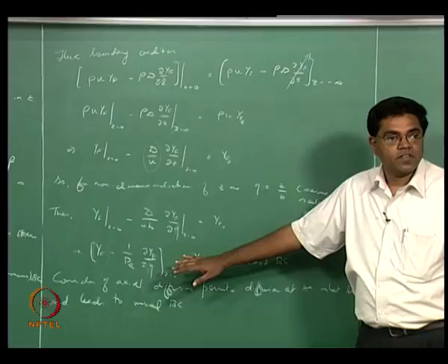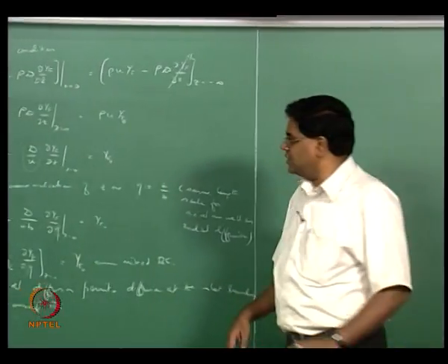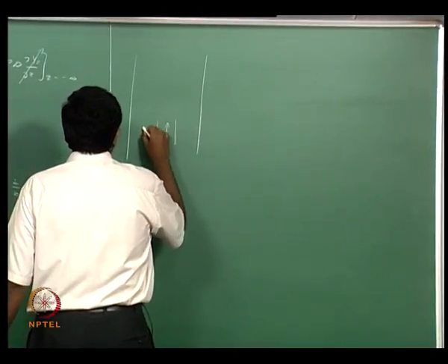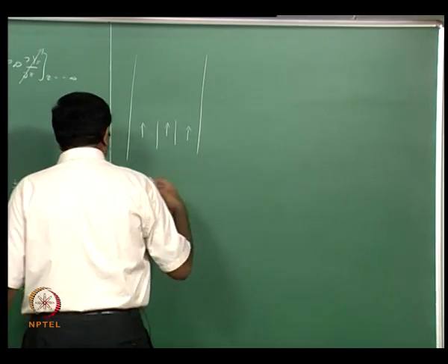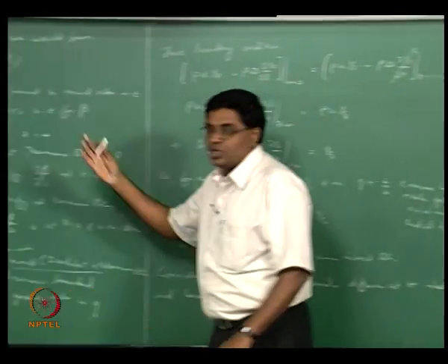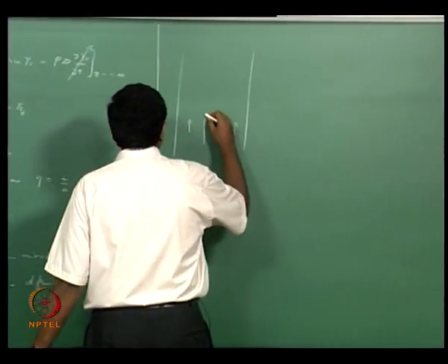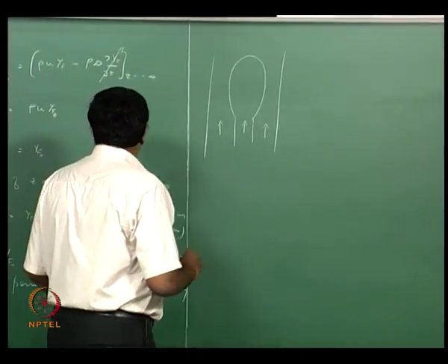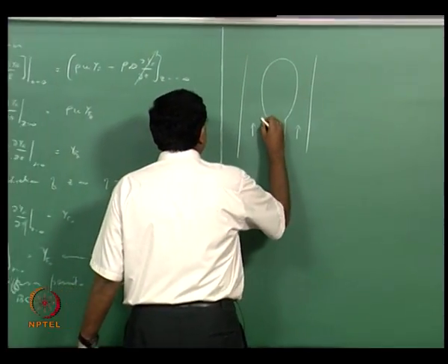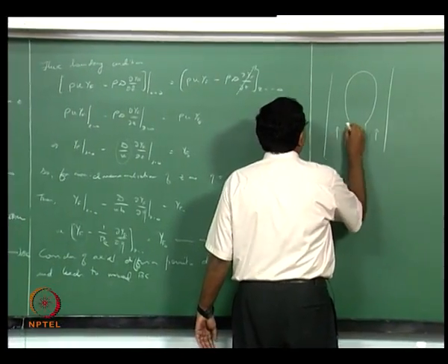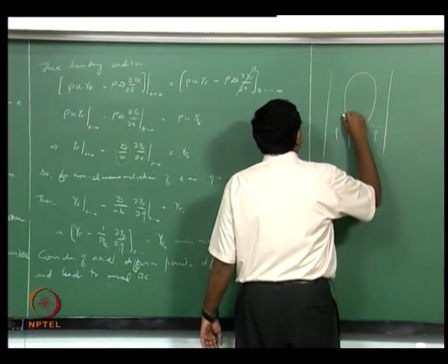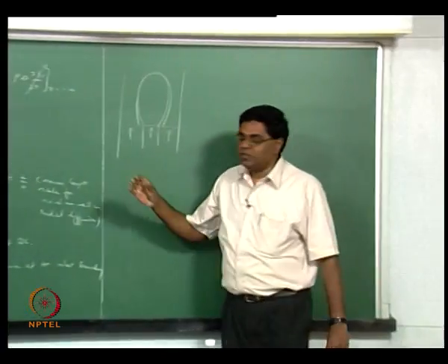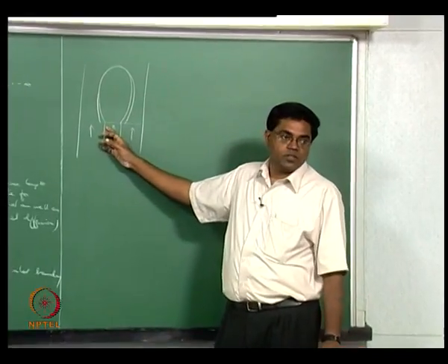How does the flame look, right? The answer is, if you now had a Burke-Schumann solution with axial diffusion and Dirichlet boundary conditions, if you had a flame that looked like that, your flux BCs are going to make sure that of course your domain starts here, right? Your flame starts somewhere there. That means the flame is no longer going to be attached to the rim of the burner.